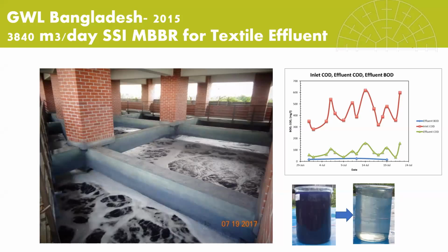Temperature is also a critical factor in textile treatment. Depending on the collection system, the temperature could be anywhere from 35 Celsius up to 50, 60 degrees Celsius in some cases. When you start getting into dyeing facilities, print, dye, and finishing facilities typically have pretty high temperatures. So temperature is a main critical consideration in biological treatment design. In most cases, what we're looking for is to try to get the temperature below 37 Celsius for biological treatment.